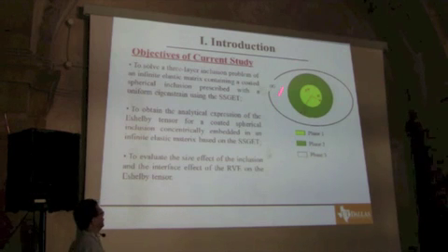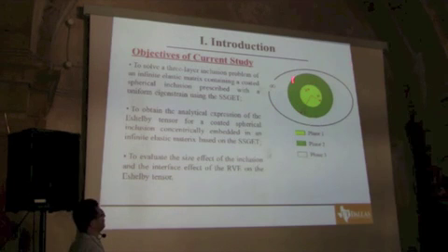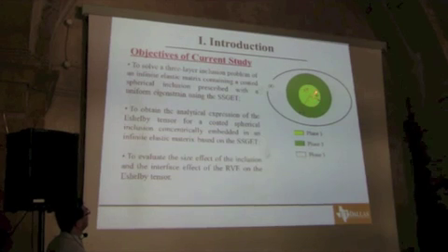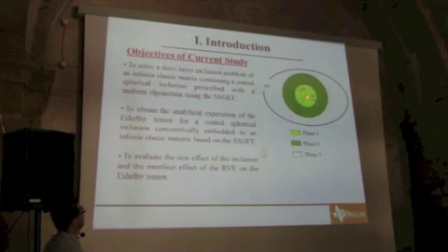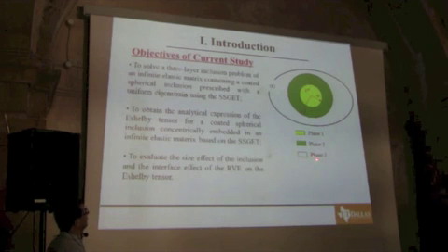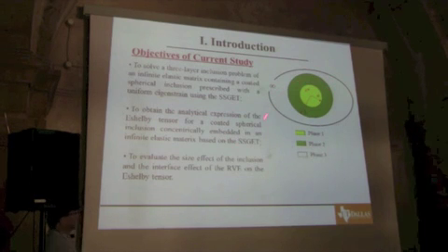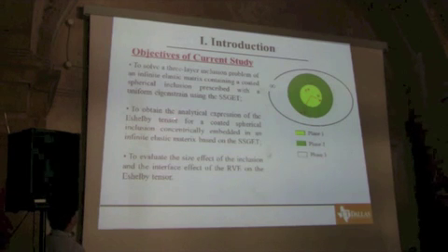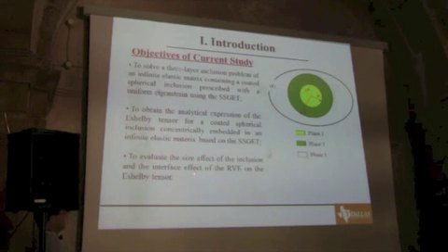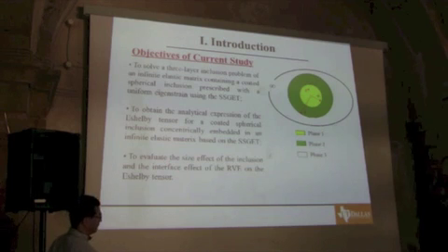So this is the problem we are going to present today, and the paper has not been published. We are getting ready to submit the paper. And essentially, we have 3 layers. The first layer, phase 1, is a sphere with radius A, then phase 2 up to radius B, and phase 3 is an infinitely large domain. So we want to solve this problem exactly by treating it as a boundary value problem, and after that, we want to evaluate Eshelby's tensor by just using the definition provided by Eshelby.